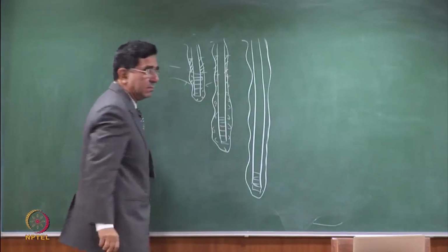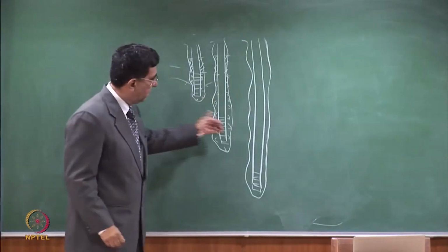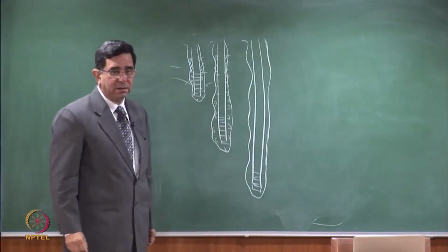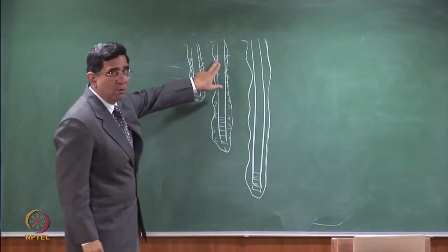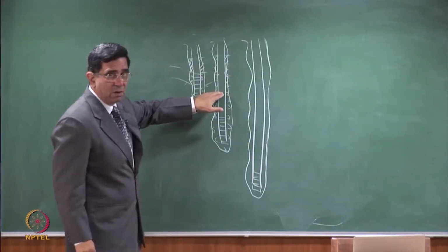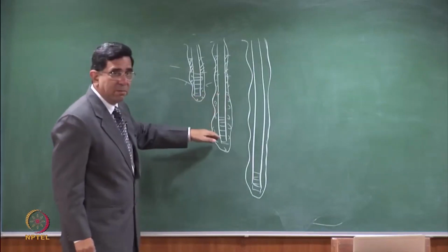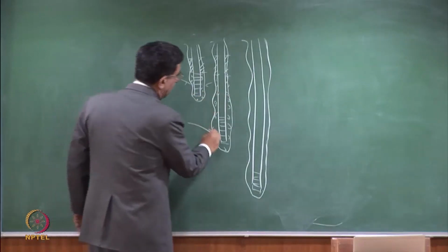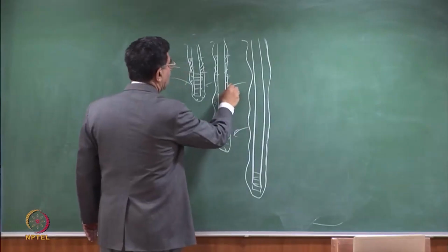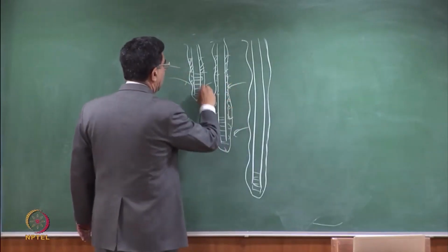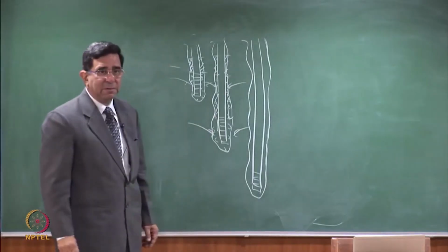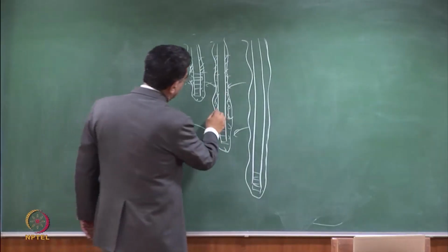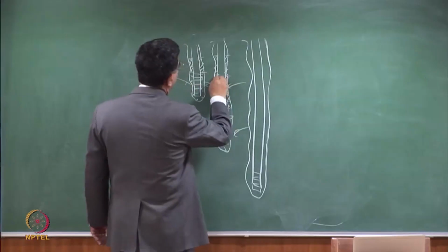Is this correct? My screen is here, water will come from here. No, this is not correct. When I start to pump out the water, the water level inside will fall. Water will want to come in, it will come from here. Definitely it will come from here. But it will also come from here, and since there is gravel here, it will fall down and mix with it. So your seal should be, all this should be sealed.